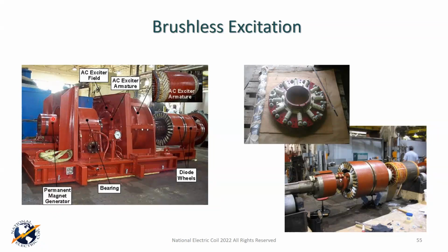But the other thing that happens, and what a lot of people don't know, is that if you remove one of the magnets from the assembly, you actually compromise the magnetic field in this device. You have to get it reassembled, jog it down or short it out, and then you have to remagnetize it above the Gauss level you were looking for, and then you jog it down to hit the target Gauss level.